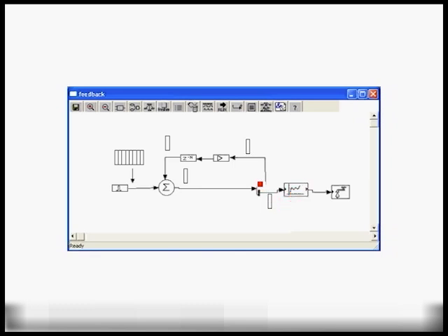So unless your simulation is built up of very primitive blocks which do simple operations, this is not, in fact, an inefficient model. In fact, it's very efficient because each block, for example, you're doing an FIR filter, you're doing a convolution, most of the time consumption is in that block doing a convolution on a per sample basis, not the fact that it gets called multiple times.